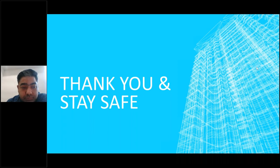Based on factors like U value and R value of the facade, we can understand how much reflectivity and insulation the wall has. We also look at thermal bridging and try to reduce it, improve your overall insulation, have a lesser amount of glazing or glass areas for heat to come in, or try to have glazing with better U values. That's how we look at it.